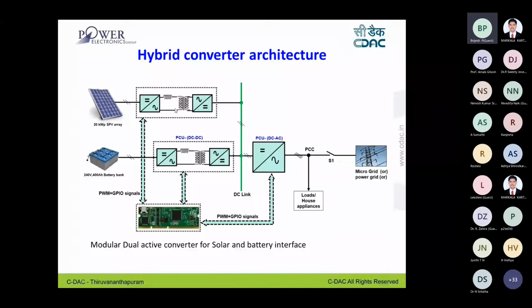In the previous module, we had the isolation at the 50 hertz side, that AC side. So obviously that will be bulky transformers. But it has its own merits, like during a fault, that transformer can provide a fault impedance. But especially when we're thinking about a remote location, the form factor should be reduced.